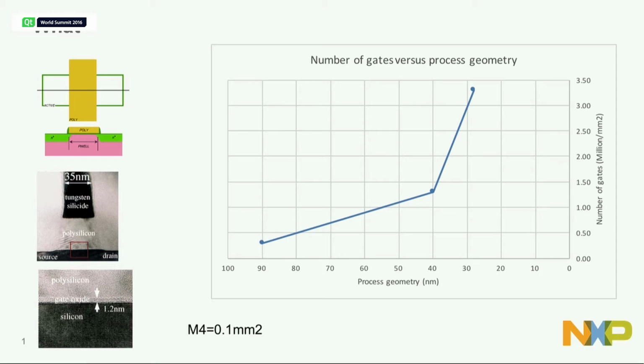So the idea is making these gate oxides really, really thin. This is in 40 right here, and I'm working on stuff now that's in 28 FDSOI. And you hear this in the news all the time. I have a story from my son. When he was a little kid, he liked to play games on the PlayStation, and he tells me, "Dad, the new PlayStation's coming out, and it's, I can't remember exactly, it's in 40 nanometer FD silicon on insulator. Isn't that awesome?" I go, "Do you know what that means?" "No, but it's awesome because they're telling me it's awesome," right? Which I thought was really funny.